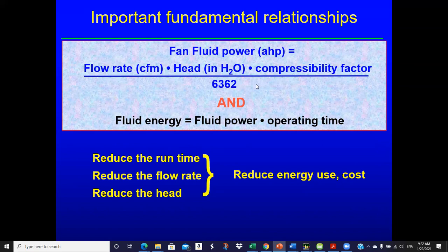And then the motor is 92% efficient, so you've got to divide by 0.92 to get the efficiency of that. And then if you have a VFD or something, there's inefficiency in that. So you can back up to the point that you can calculate the power required to put into the motor, in order to make all of this happen, or into the drive.